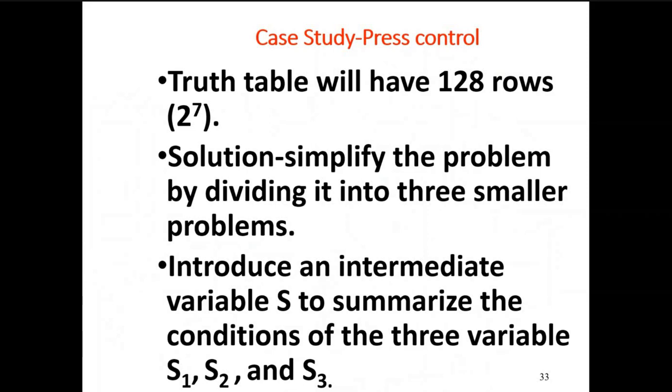The first thing to do is look at those panic switches, S1, S2, S3. What are they? They are actually 3 switches. Are they independent? Yes, they have to be independent switches. They are not wired in series. They are wired in parallel for this operation. You trip one of them, boom, I want an output, which a parallel circuit will do. But not to be confused with wiring switches in series or parallel. Just for now, assume each one is producing its own output.